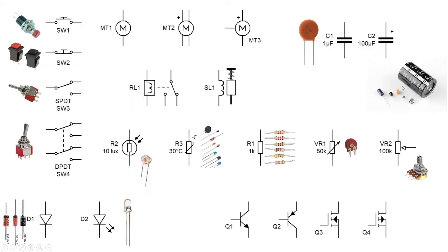And then if they're of a bigger order, they will actually have to be one way round. So these barrel shaped ones come in all sorts of sizes, right up to this size. They have a plus sign, so they need to be the right way round as well. So you'll notice this band across it is normally a negative to depict which way round. Now, big ones like this, you've got to be quite careful with them, because they can discharge very quickly as well. So you don't want to be touching a large capacitor like that that's charged. It'll give you a nasty shock.